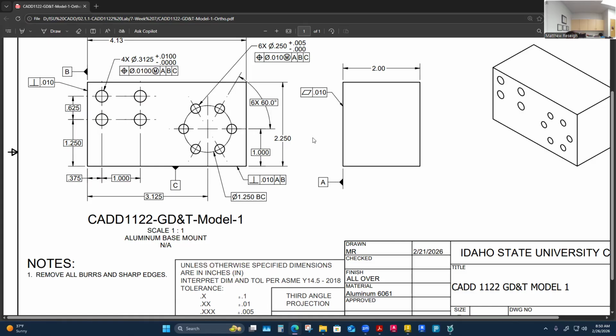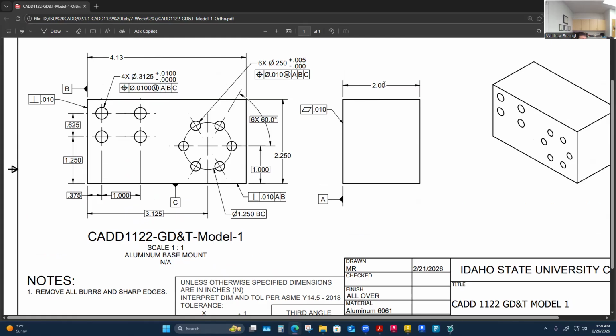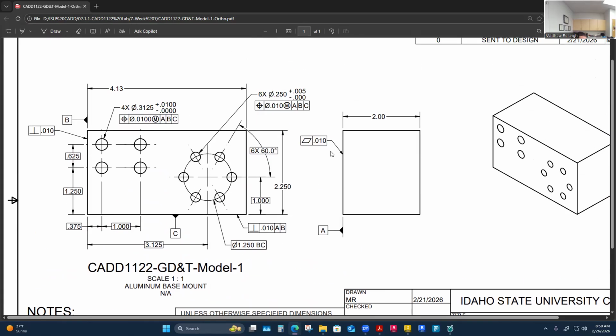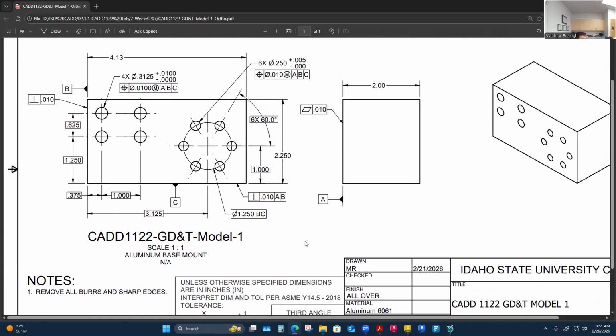So if that 2 inches looks like I have a plus or minus tolerance of like 2 decimal places, I have like 1/100th that it could depart from 2 inches. If it was 2.01 in size, it would be acceptable by my tolerance. But at 2.10 size, I'm at max material condition, and none of this 10 thousandths flatness would be able to be applied. That's how that would work, to reinforce the concept we were just talking about with the straightness on that shaft too. At 2 inches, I would still be allowed that flatness if my part size was produced at 2 inch.